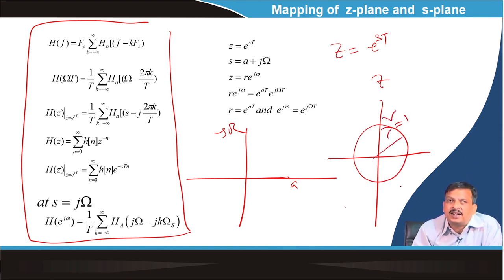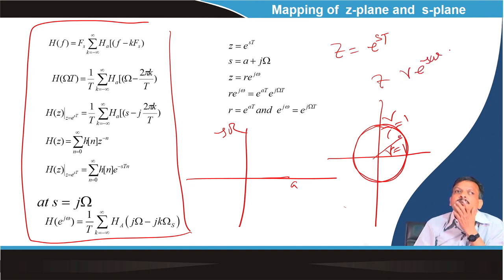So, what is the stability criteria? All my poles must be inside the unit circle. Okay. So, the radius is R equal to 1. All poles must be inside the unit circle. How do I define a pole? It is nothing but R e to the power j omega. That is discrete, normalized discrete frequency. And when I define a pole in here, this is my pole. So, this is nothing but a plus j omega.